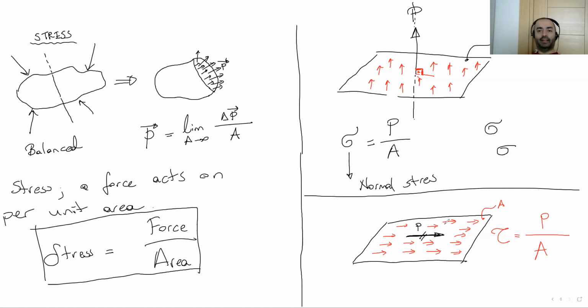Why? Okay, at the end of the day, stress is stress. Force over area. Why are we making these differences? Why are we dealing with normal stress or shear stress? Structural members have different shear and normal stress capacities. That's why we do this branch.